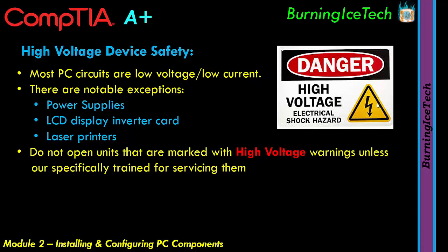Even if it's unplugged, those capacitors store very large quantities of electricity for a very, very long time. So you might have a power supply lying in a box somewhere in your house. It's been there for years, and you might think to yourself, what's the harm? Trust me, it can still either kill you or put you in an intensive care unit.